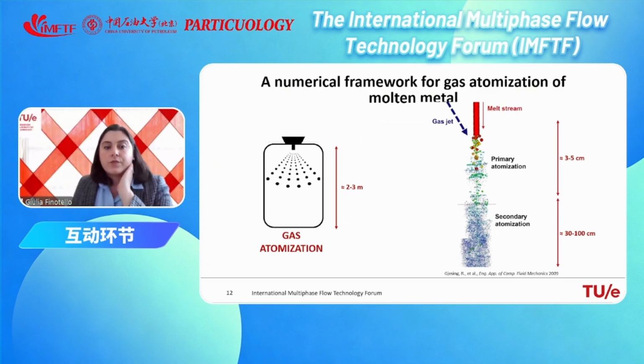Well, yes, of course, that's where the gas jet is impinging on the melt, so close to the nozzle. Of course, there are several melt-gas interface dynamics, and that's also what I tried to show you in the images later on. Depending on the condition of the process, of the gas and the melt, what you usually see is that you have a recirculation very close to the nozzle.